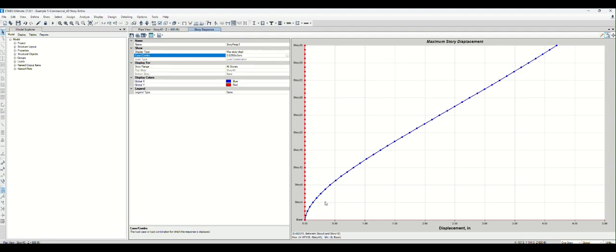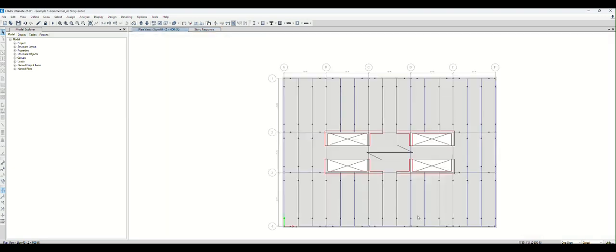So this is our deflection, which this model has a strong axis in X direction. Deflection under the wind X, service wind, I think we have a 4.19 inches deflection, but Y direction, let's check, 26 inches. So we have a lack of stiffness in Y direction. You can already see it.